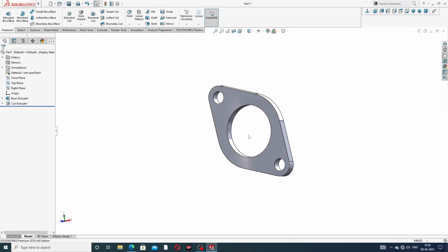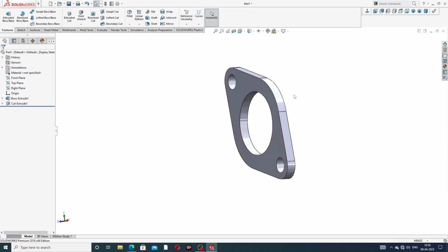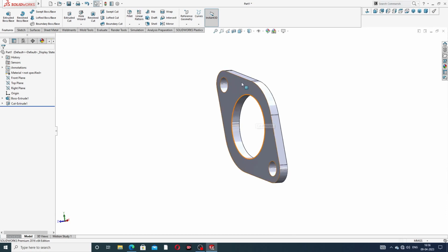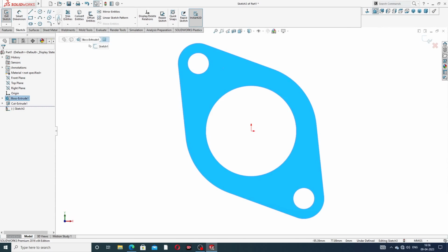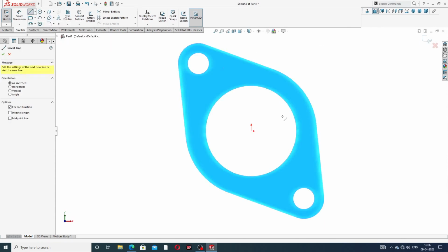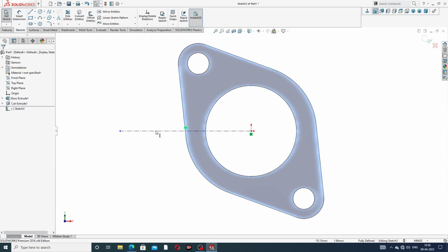All of this is one body in a clear design, but now use a pattern; the pattern count is 4 and this body is 4. Select this face, sketch normal, and use a reference line. The reference line is very important because this is used for the pattern, and this line is horizontal. Okay, this is perfect.